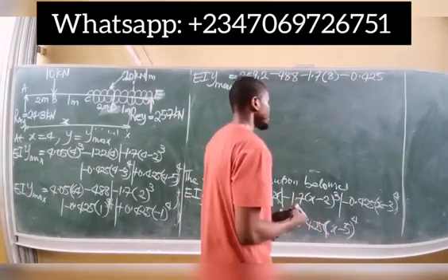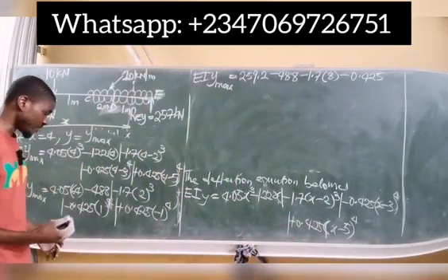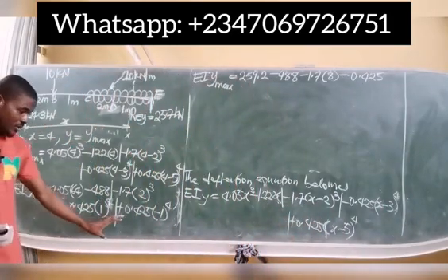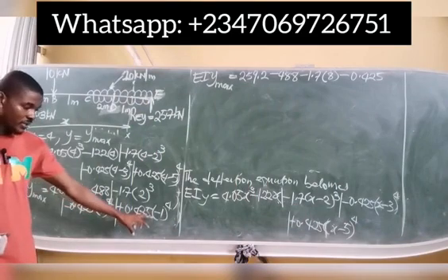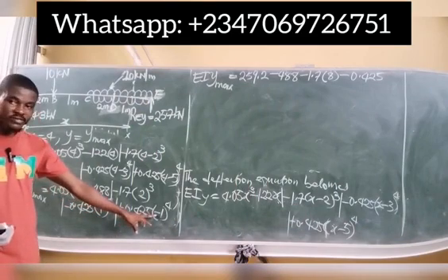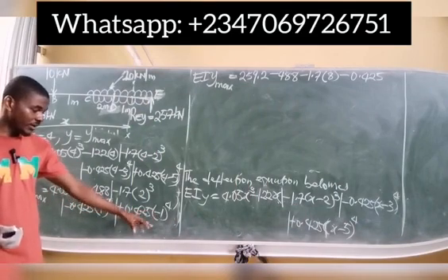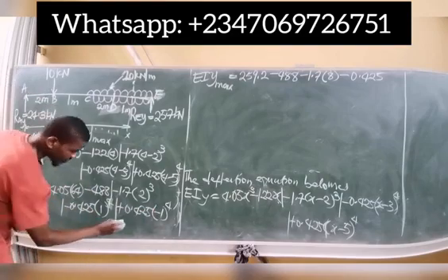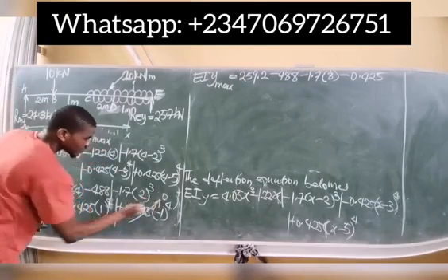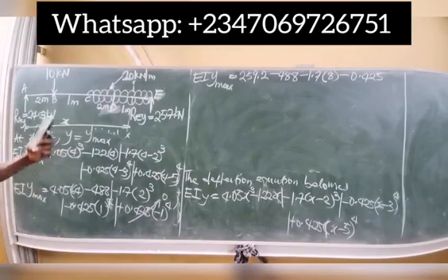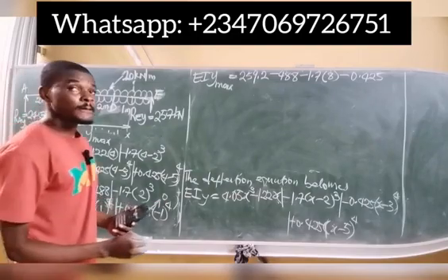That value multiplied by 1 remains the same. Then if we examine this other bracket, we have minus 1 in the bracket, and according to Macaulay's theorem, if you have a negative value, automatically everything there becomes 0. So this is completely 0, and I'll just work with that.